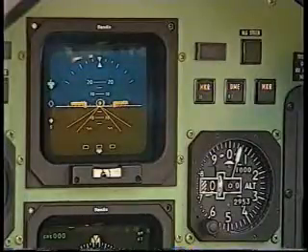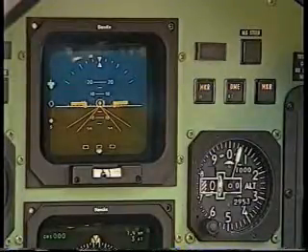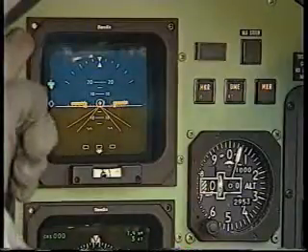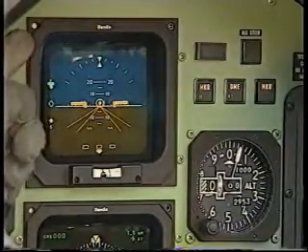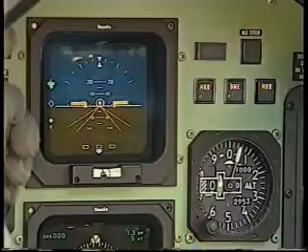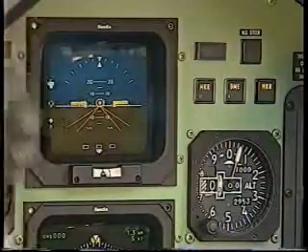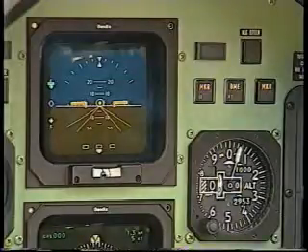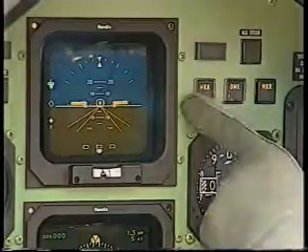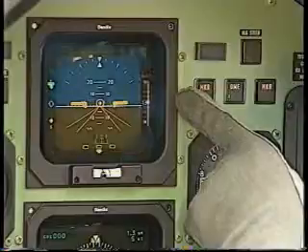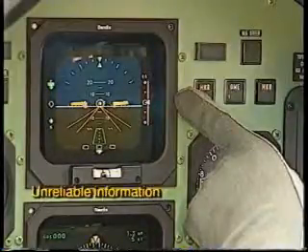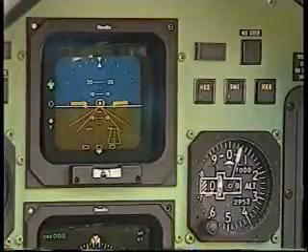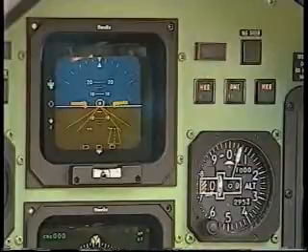The final component on the EADI is a photocell up here. It provides a small amount of brightness compensation to the display unit. Now, any unreliable information is highlighted in red, either red words, red lines, or red crosses. For example, in this case, the glide slope is unreliable and has a set of parallel lines running through it. That's the EADI and what it displays.